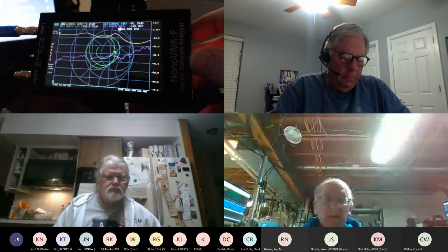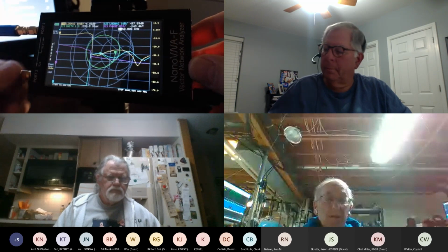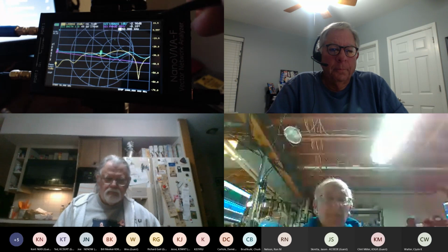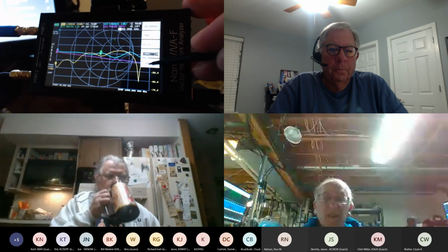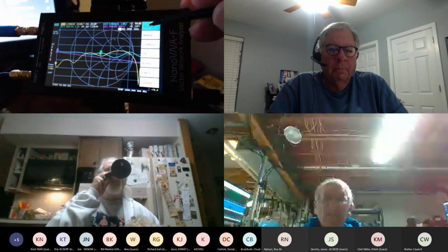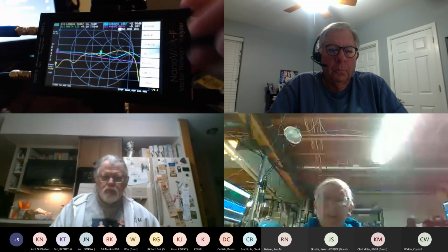And we're going to calculate, in this case, or look at a through measurement. So we want to look at the logarithmic magnitude of the S21 or through parameter, transmission parameter. And so let's select that so that we can look at the correct scale here. We'll go into display and trace. We'll select trace 1, go back.